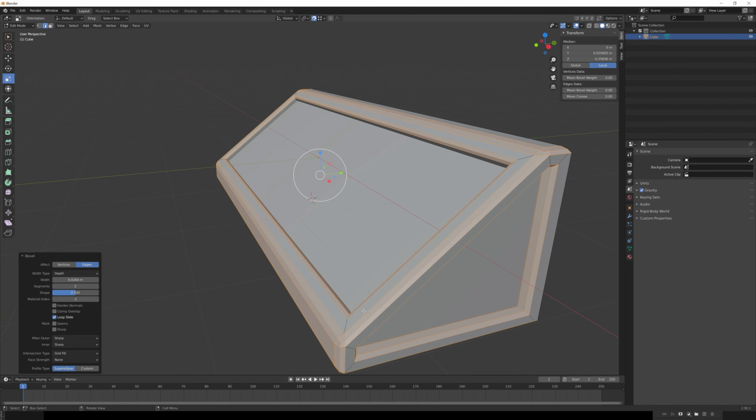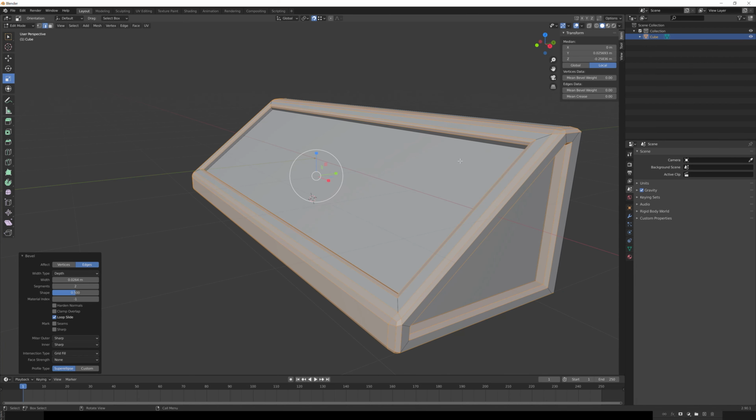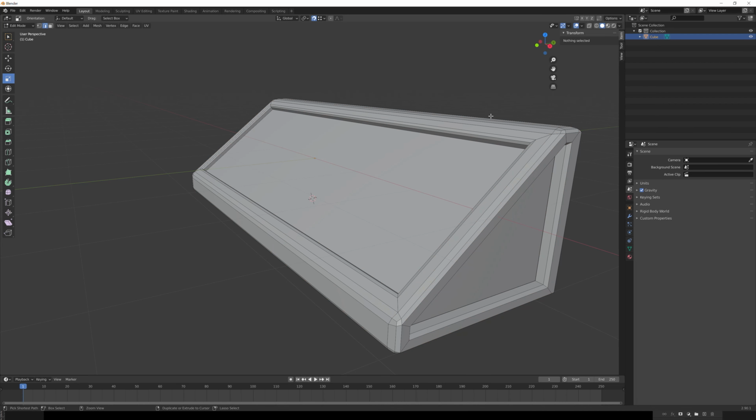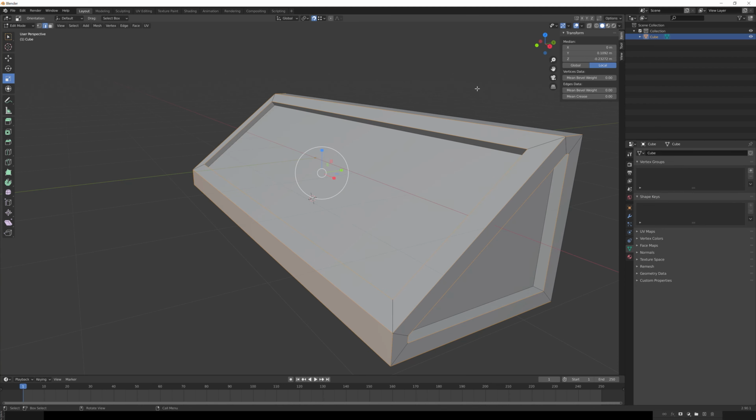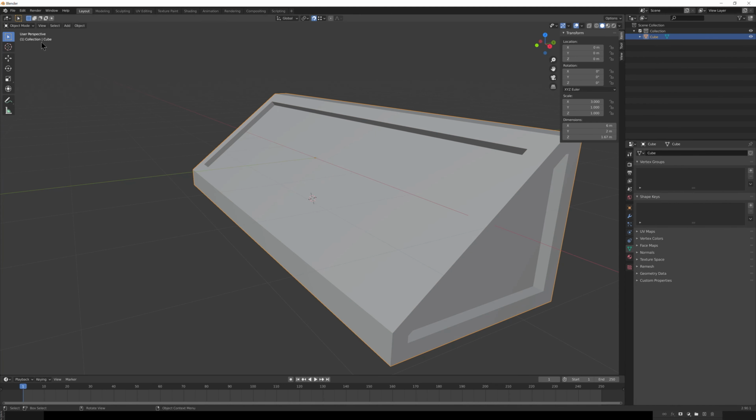However, what you're going to notice is it seems like this object is being skewed funny. And the reason for that is because we have a scale transform being applied to this object. If we want this to actually look correct, what we should do is apply our scale before we do these operations. So I'm going to go ahead and hit Control and Z to undo that operation. Let's get out of edit mode by hitting Tab again, or coming up to this little drop down here and changing that from edit to object mode.